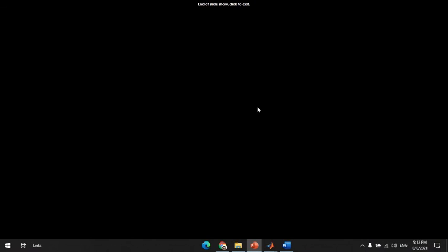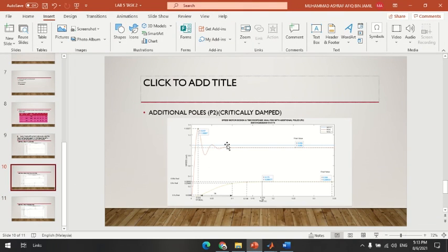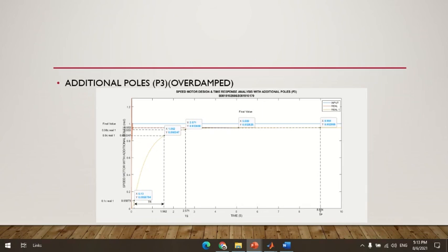And I assume that for the P3, it depends on the accuracy which we are looking for. However, we assume that the potential exponential decay is negligible after 5 time constants. Thus, if the real pole is 5 times further to the left than the dominant poles, we assume that the system is represented by its dominant second order pair of poles.